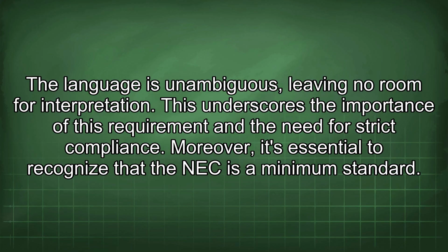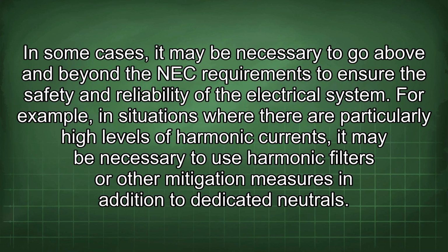Moreover, it's essential to recognize that the NEC is a minimum standard. In some cases, it may be necessary to go above and beyond the NEC requirements to ensure the safety and reliability of the electrical system. For example, in situations where there are particularly high levels of harmonic currents, it may be necessary to use harmonic filters or other mitigation measures in addition to dedicated neutrals.